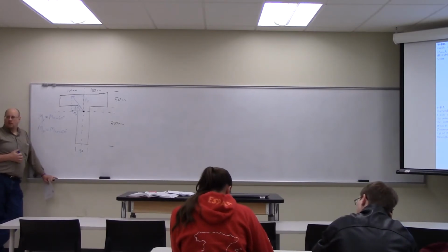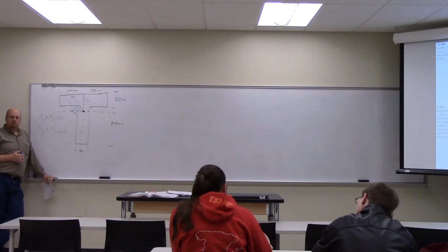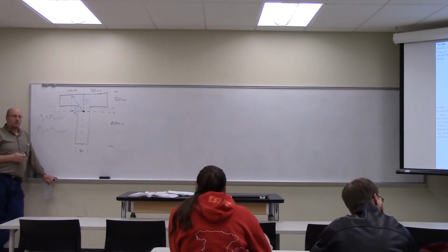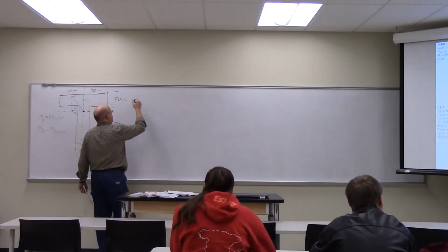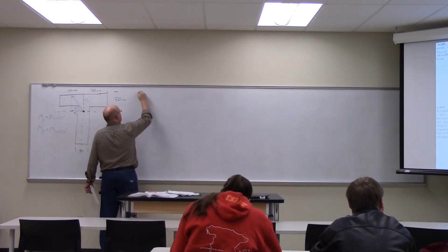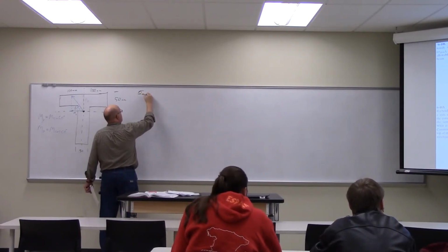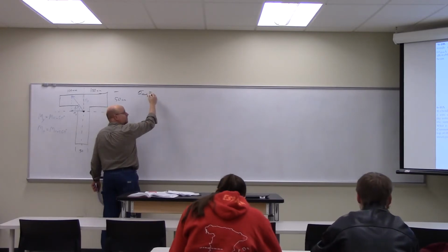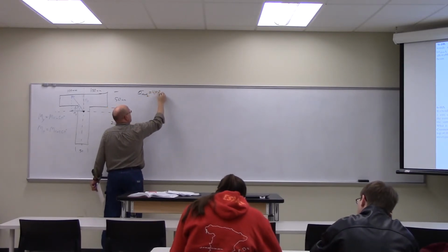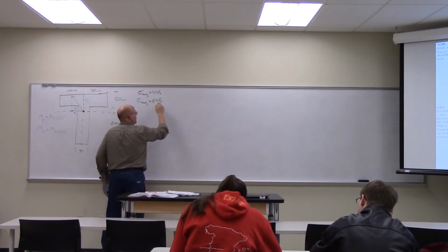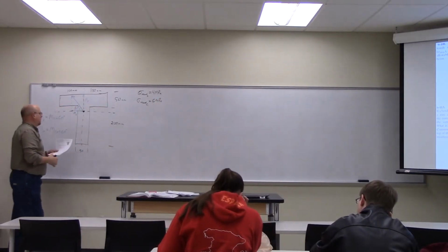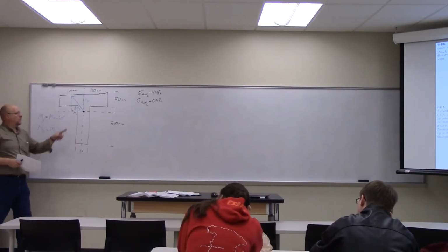What's the limiting factor here? The stresses, right? The sigma. We know that we have a maximum sigma. Sigma allowed in tension is 4 megapascal, and the sigma allowed in compression is 6 megapascal. That's our limitation. So somehow we have to express a relationship between the applied moment and the stress.